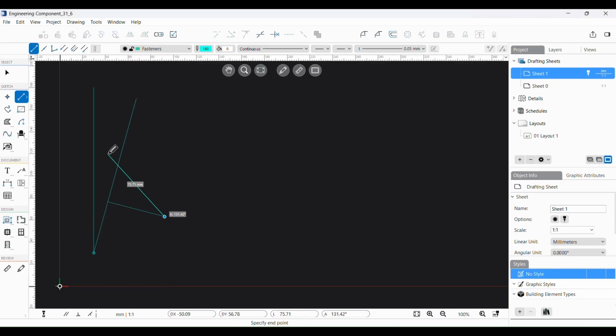Furthermore, when you place the pointer over a segment, this function stores the angle of that segment, displaying the corresponding parallel and orthogonal guides. When tracing the line, just place the pointer over one datum point of that segment, endpoints or midpoint, to display the alignment.